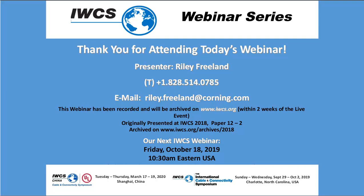Next, in the event of an unlikely failure, is this application easily repaired or would it require a complete redeployment? Right, so there are repair strategies in place that would require the cable to leave the trench, go to a curb, and have some splices done. But there is a repair strategy that would allow the cable to be fixed and not redeployed entirely.